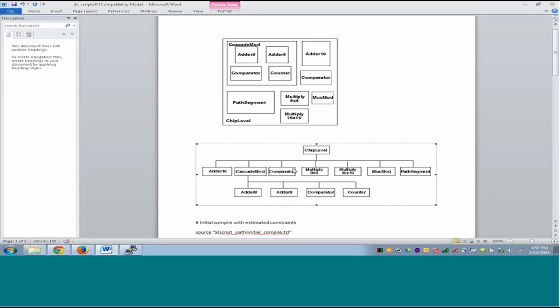Later, in this chip netlist, I will remove the black boxes again using Design Compiler. I'll read the complete netlist of USB, HDMI, and CPU, and write out this file. This way, none of the commands in DC, except the last one, will see the complete design. So you won't have runtime issues. This process can be done in a few minutes to a few hours.